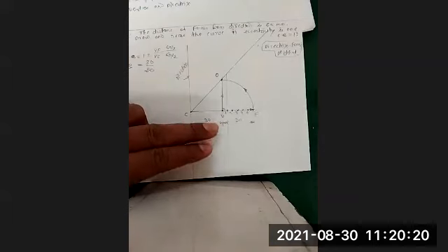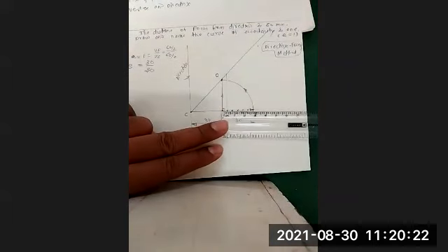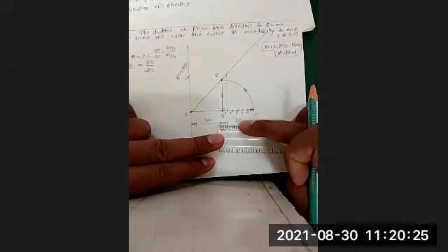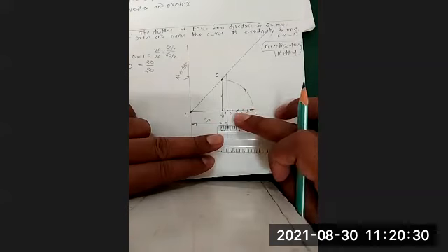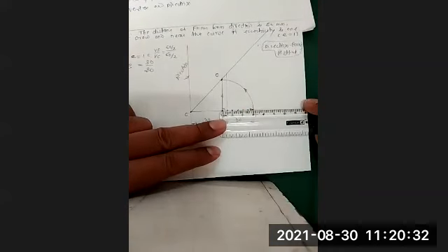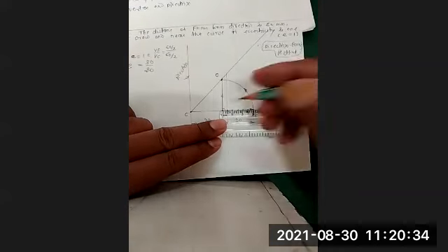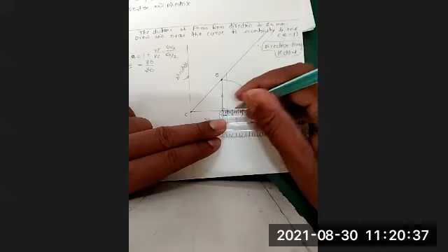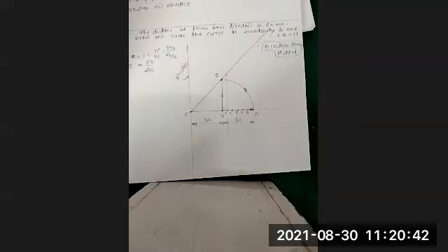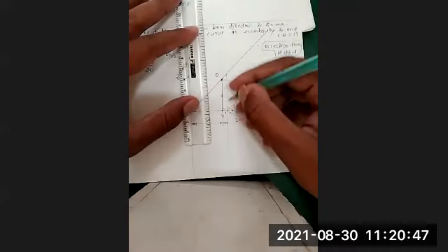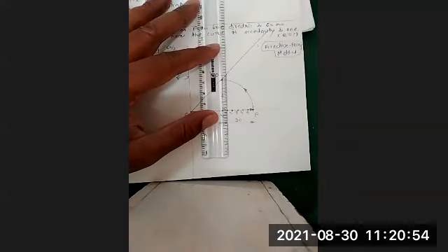I suggested you can take the spacing maybe 5 millimeter, 6 millimeter, 7, but as the number is 30, it is quite easy to divide this into equal spacing of 5 millimeter. So we have taken the first point at 5 millimeter, second point at 10, 15, 20. Likewise, we got this number of points. Now the next, as I said, this line I have taken perpendicular to CF, and passing through point 1.